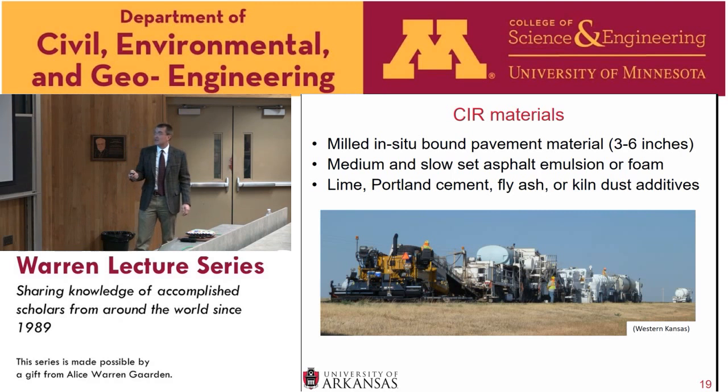So within this train, at the far right-hand side, you have a truck ready to replace one of the trucks in the train. It looks like the first truck of the train probably has the asphalt emulsion. I would assume this second truck is either a water truck, a dry additive truck, or additive in a slurry form. Then we'll go through all these pieces of equipment in more detail, but you have a milling machine, a crushing machine, a pug mill to mix all these materials together, and then a paver in the back. So you have a bad road in front, and a brand new road in back. This train is probably about a quarter-mile long, so it's quite a bit of distance.